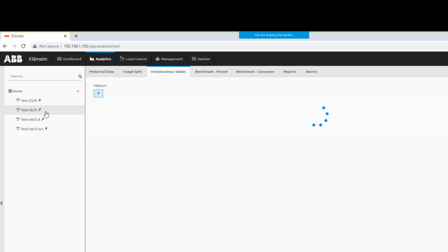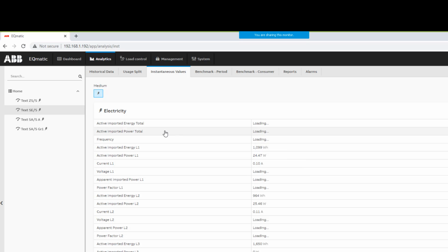For the energy actuator, of course, I have some more functions. Here I get additionally also the voltage, for example, I get the frequency and so on. I get the meter values here total for the complete device, at the moment 50, because my output A and B is switched on and my output C is off. You see here power, output number C, which is here labeled LSV, is 0. So, and here we have 25 watts channel B, 25 watts channel A equals 50 watts. Good, so far the so-called meter values.